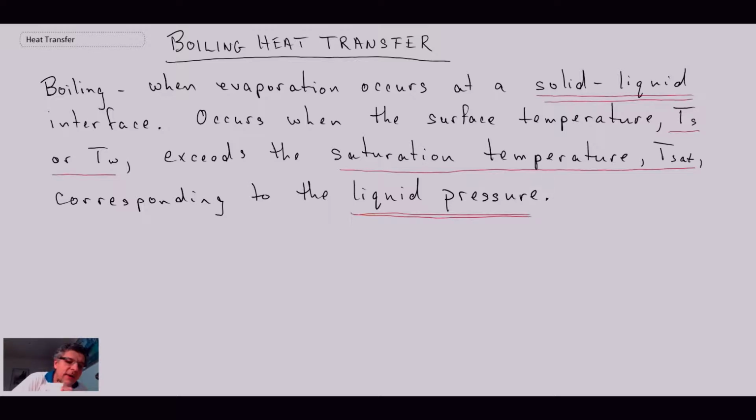And when we look at boiling heat transfer, I mentioned that the convective heat transfer values are very, very large, and we'll see that both for boiling and condensation. But to describe, we just use Newton's law of cooling like we've done before. Now, for our delta T, we're going to have our surface temperature, our wall temperature, and the other temperature is going to be the saturation temperature. So typically, it will make sense. You have to have the wall at a higher temperature than the saturation temperature in order to have boiling take place. And so that is the delta T that we will use.